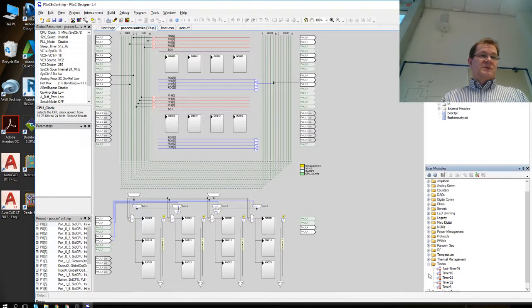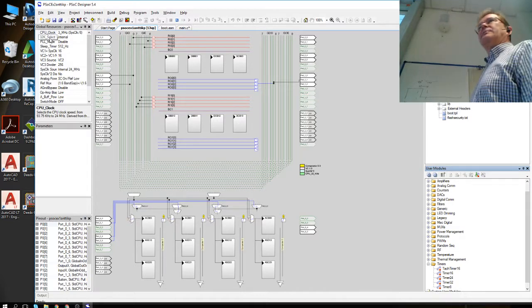Let's see, timers. And now we need to do some calculus, in order to get about a 2 Hz interrupt rate. We actually have 2 clock sources there. The internal 32K clock on the global resources could be used.